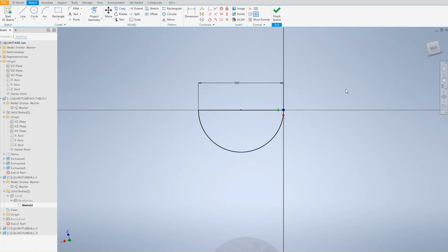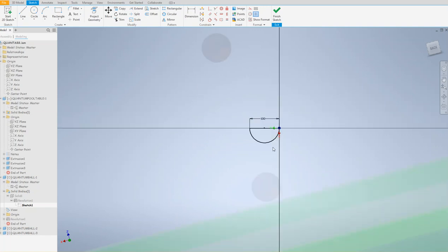That needs to be created with the half circle. You create one circle and then you trim it off after you draw the diameter. And you need to have the circle so that you can use the revolve command to generate a sphere, and the dimension for that is 100 millimeters. Realize that the diameter of the hole is 130 millimeters, and a 100 millimeter size ball will fall through the 130 millimeter hole. Once you generate this, you simply go and use the revolve command.